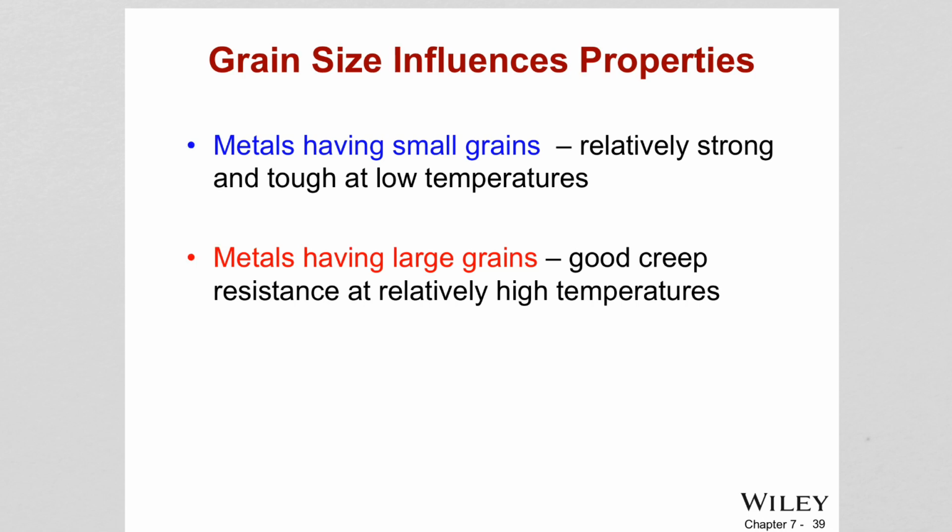However, the material can still plastically deform, and this is called creep, because the temperature basically affects the stresses required for the plastic deformation to happen.